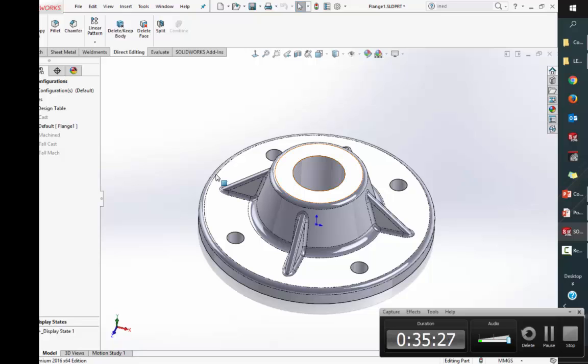Okay. Now coming through, you'll see that there's a symbology change here as well. You'll see that there's a little box next to default, and you'll see the other ones fall underneath the X. You can intermingle design table configurations and manual configurations together. It's actually something that I do frequently, usually for simplified parts, for FEA versions and stuff like that. It's not something I want to control through a design table. Now, I will go ahead and go to the machined. That looks good. I got the cast.